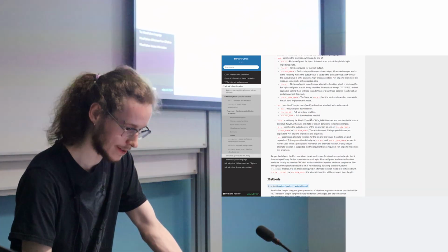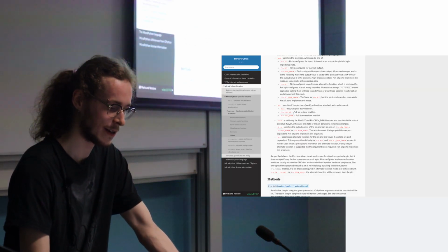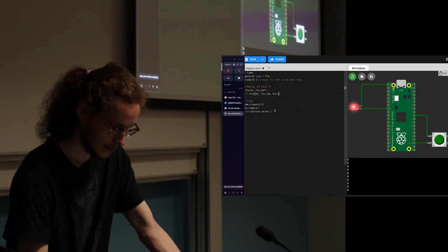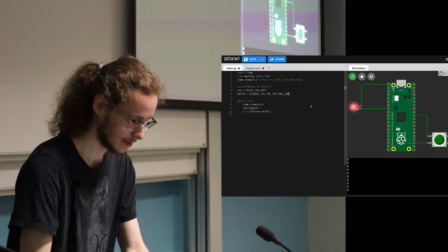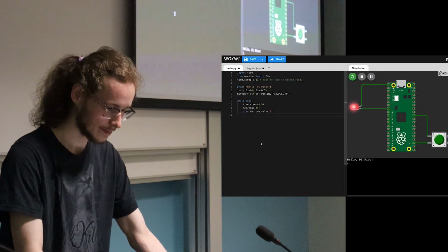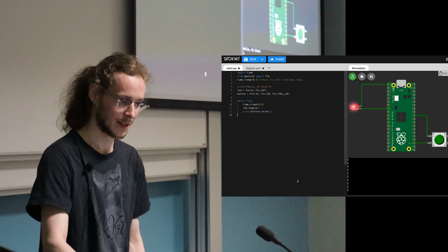And okay, it is just that. So we want to add a third argument, which is Pin.PULL_UP. Now we run it. Okay, and now it's reading ones all the time.